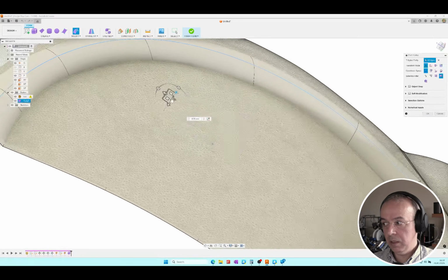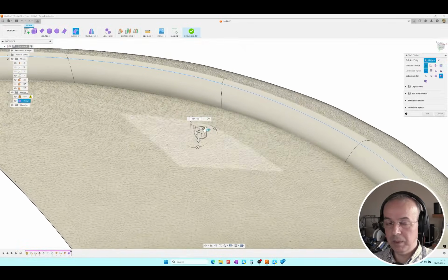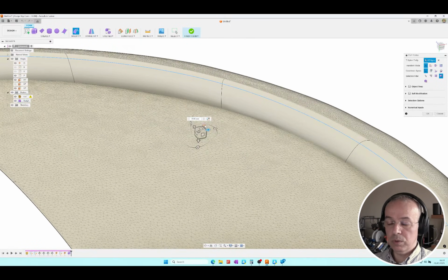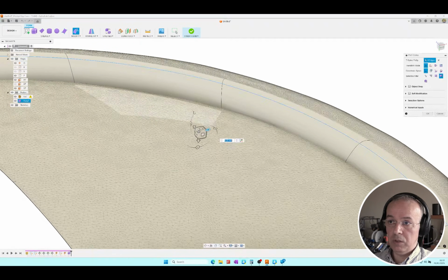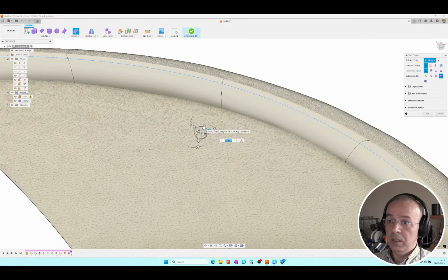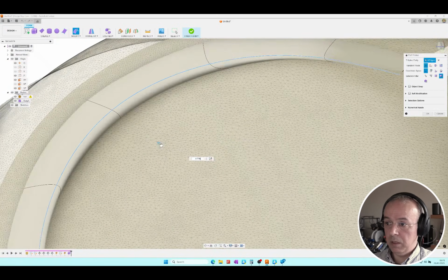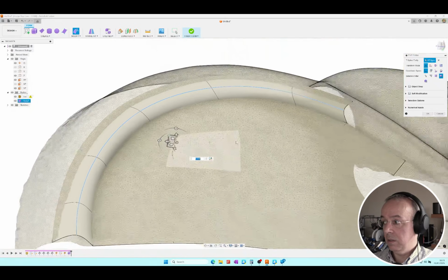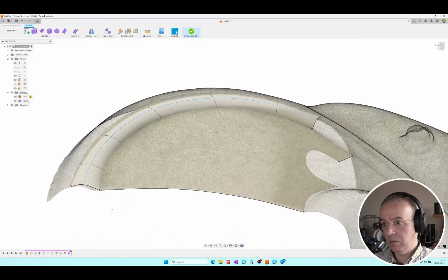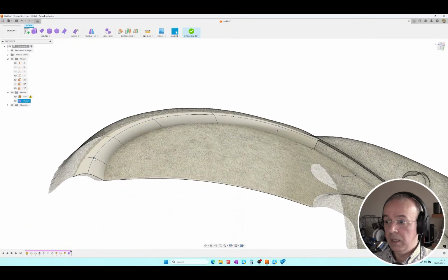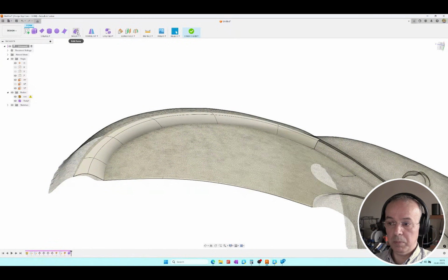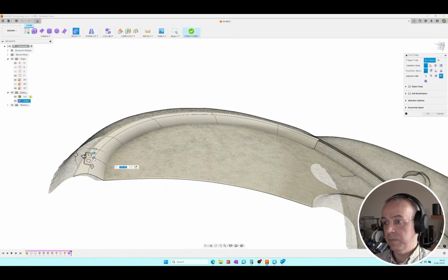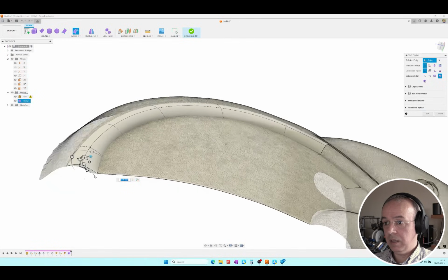I'll switch back to selection mode to try and understand if using scale is viable. No, it's not viable. Let's use the scale option at the corner of the gizmo, which will adjust the scale in the plane. Both scenarios essentially involve the scale command. Sometimes this tool solves the issue, but not in this case, given the three-dimensional nature of this part of the piece. Here, the only alternative is vertex by vertex manipulation. It's not complicated, but more labor-intensive.